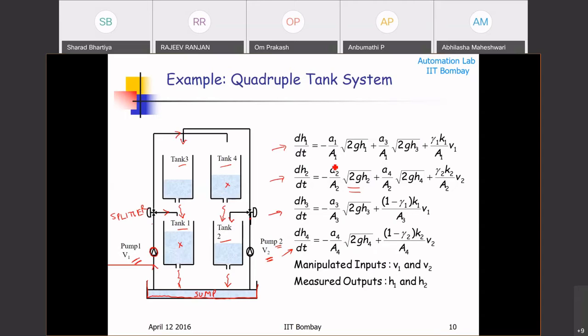In fact, if you use these equations and you have tanks which have very little level in them, you will find that the square root nonlinearity can be quite steep, because if you plot the square root nonlinearity, you will see it looks like this. It rises up with infinite slope, and then the slope becomes finite.